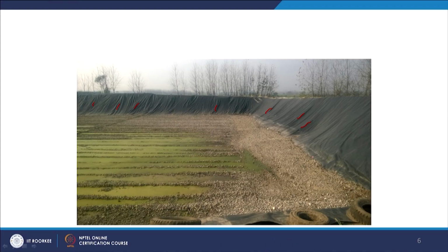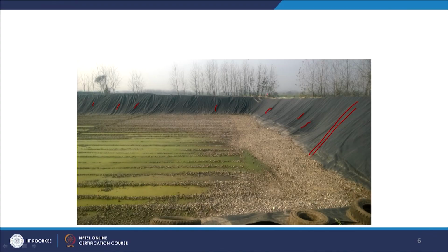And secondly, one issue in this landfill is that the relevant people did not cover the sides with the relevant layers like the HDPE layer and the clay layer too. So what happens is, over time when they keep dumping the hazardous waste, that will be directly in contact with your HDPE layer, pardon me. So I should mention that.